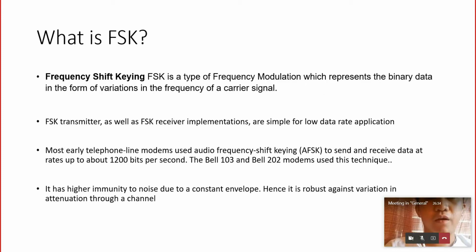What is FSK? Frequency shift keying, or FSK, is a type of frequency modulation which represents binary data in the form of variation in the frequency of a carrier signal. So yung FSK po, kamukha po ng FM, pero two-state lang po yung frequency ng carrier. Yung space and mark frequency, yung space yung mas mababa yung frequency. Then FSK transmitter as well as FSK receiver implementation are simple for low data rate application.